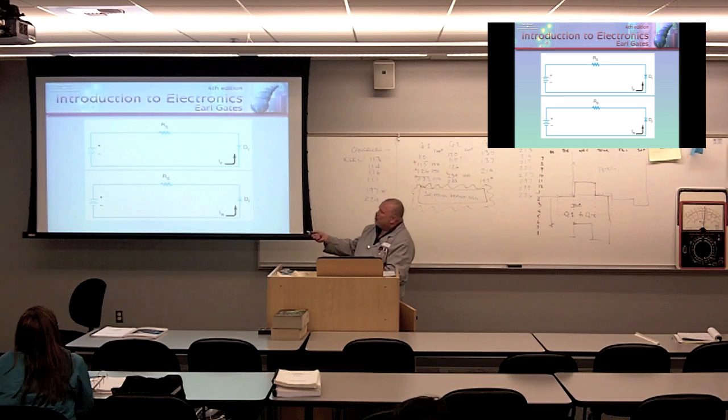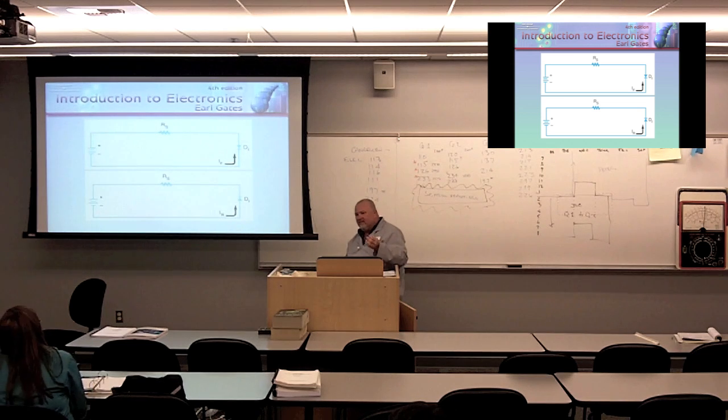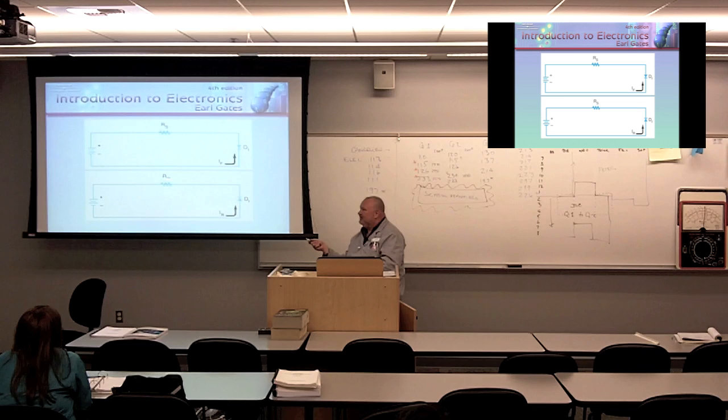Make sense? So if I've got no current flow through the resistor, is it going to create a voltage drop? No. You need current flow through resistance to create a voltage drop. Other than a small amount of leakage current, are we really going to get a little small voltage across this? Yeah, but it's going to be insignificant. If you get in there with your multimeter and measure across the diode, you're going to get 12 volts. Measure across the supply, you're going to get 12 volts. Measure across the resistor, you're going to get 0 volts, or some minuscule amount. Make sense?